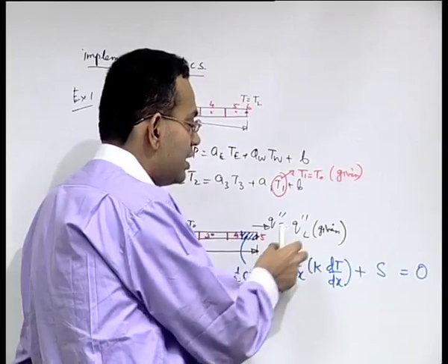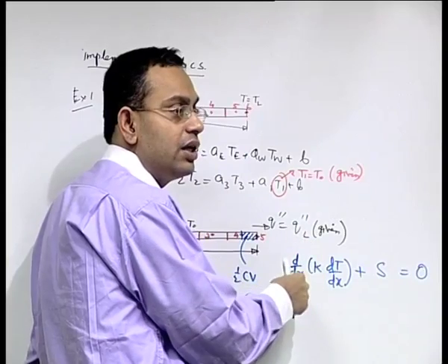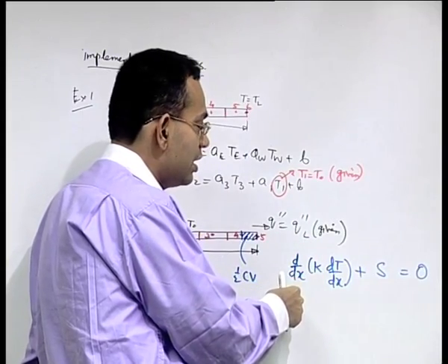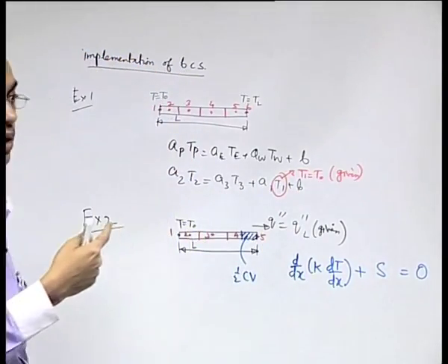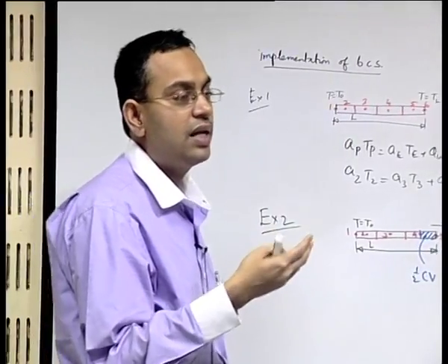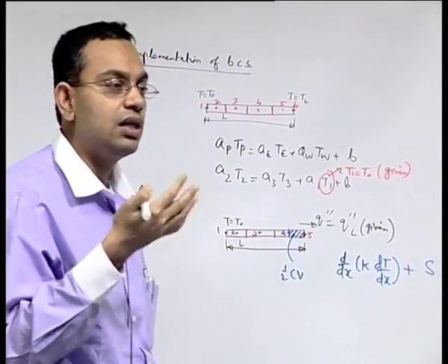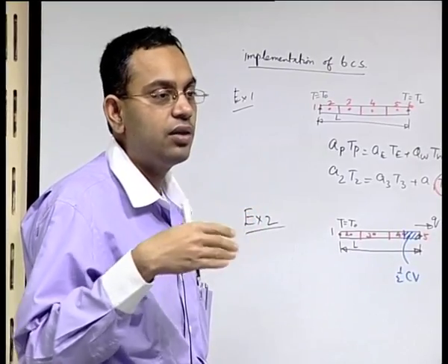If you do that, then this heat flux will naturally appear in a boundary term. The reason is that this is just like a natural outcome of the variational formulation, because in the variational formulation the natural boundary condition, which is the flux boundary condition, comes out automatically as a result of the variational formulation itself.